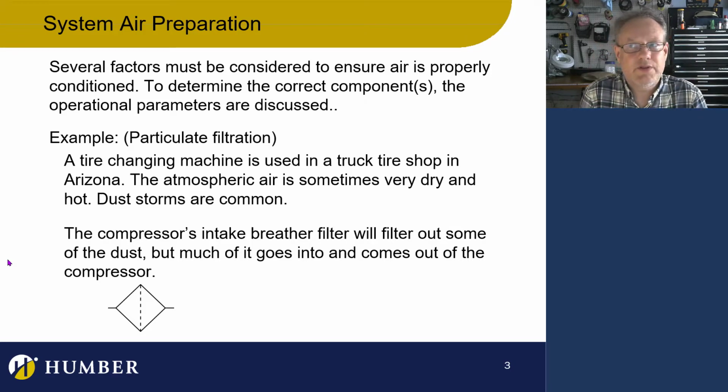Now, which one would you use for which application? Well, it depends on the air in the environment. If you're in a really moist environment, you're going to want a separate water separator. If you're in the desert, you're probably not. If you're in Arizona, you're probably not going to need much of a water separator. But all of these things actually have a water valve on the bottom of them because any kind of filter will actually take water out of the air. So you have to keep that in mind. So essentially, this is the symbol here, and you guys have to think about what's going on.